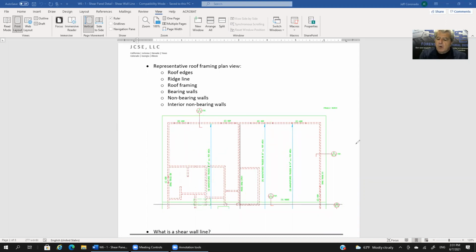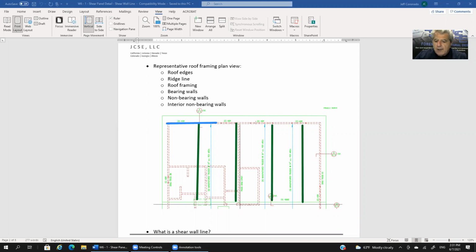Now let me get into bearing walls. What are our bearing walls here? A bearing wall means a wall that is supporting weight other than itself, so it has elements that frame into it. In this case, we just saw that the trusses go in this direction. So yes, they are landing on this wall, which I'll show you in blue. They are landing on this wall, and hence that wall supports the trusses. Hence that wall, I'll remove that blue line now.